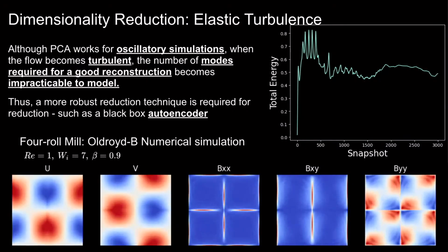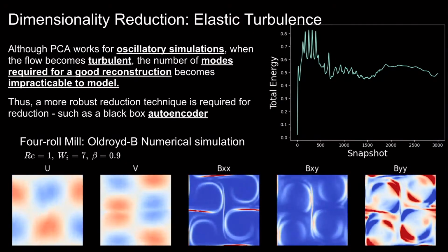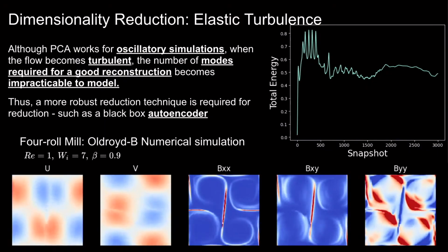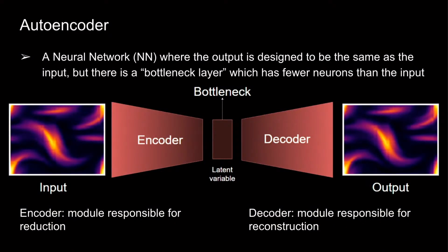But in this case, it's complex to use the PCA because you need thousands of modes. So the idea is to study if you can use a kernel PCA or other nonlinear dimensionality reduction. This is the reason we try to understand the concept of autoencoders, to include the energy analysis in this architecture or pipeline. This is just one idea about the architecture. We have the input, then you have the encoder, you create a latent variable space, and then using the decoder strategy, you can reconstruct the field, okay?